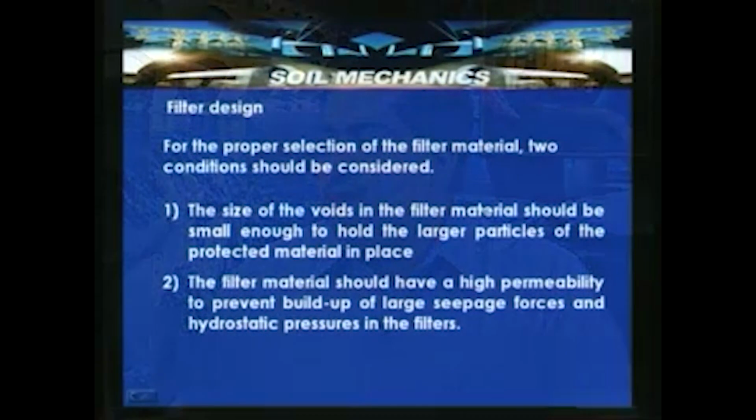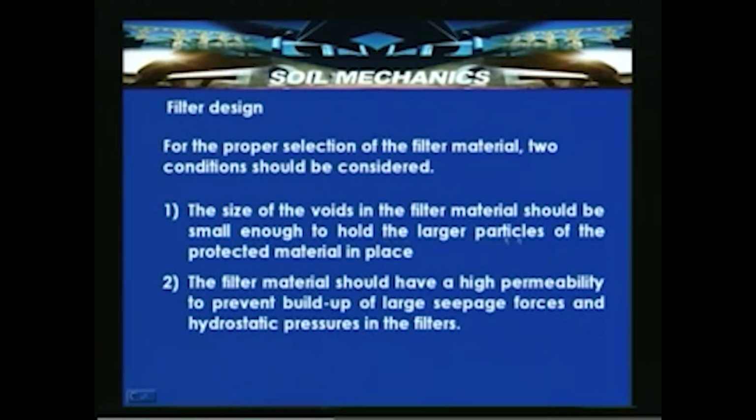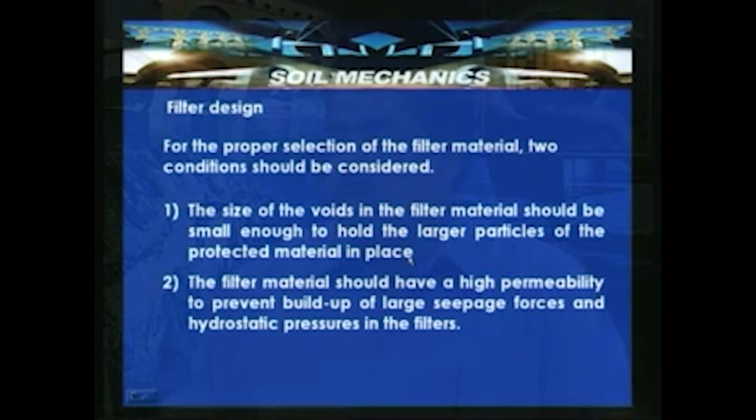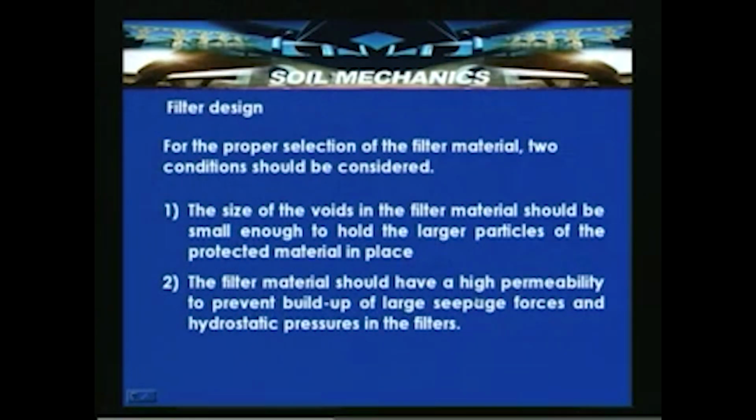So, the size of the voids in the filter material should be small enough to hold the large particles of the protected materials in place. So, that is criteria number 1. Criteria number 2 is that the filter material should have a high permeability to prevent the buildup of large seepage forces and hydrostatic pressures in the filter.